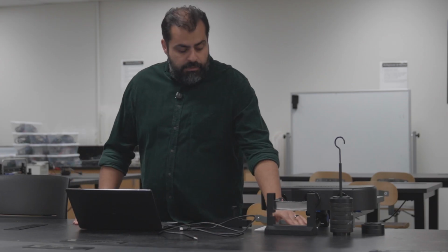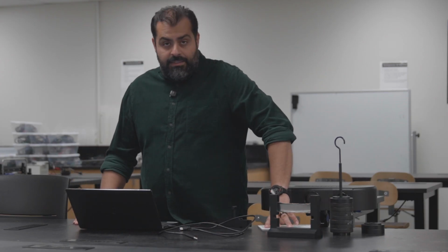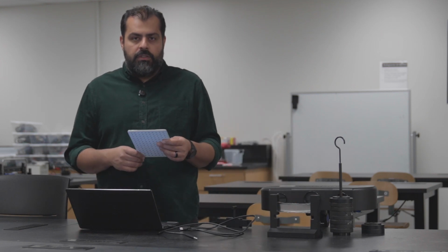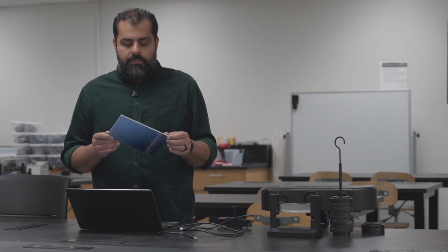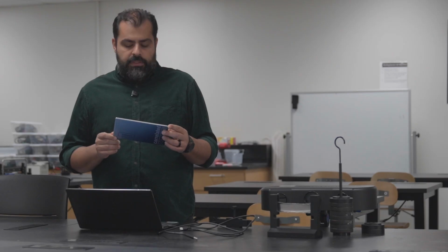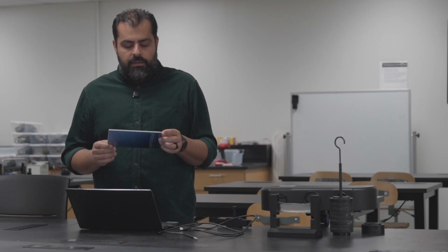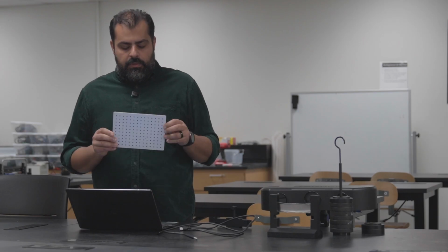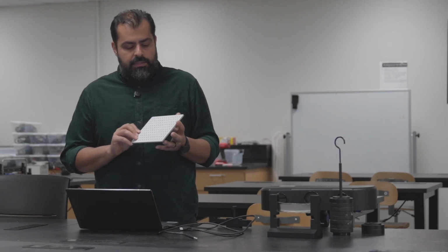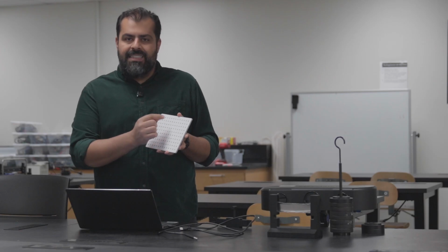This is for the sample preparation, but for the device and software preparation, we need to make sure we do a calibration. These calibration panels come with the devices themselves. The one that we have here is a 14 millimeter calibration pattern, and it has a couple of dots here. As you can see, these dots are 14 millimeters apart.